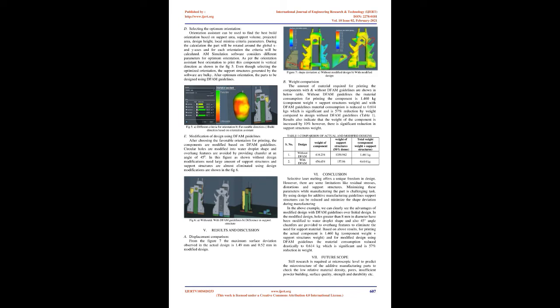To effectively implement this approach, AM simulation software is required for selecting the optimum orientation and DfAM guidelines for design modifications. AM simulation software. Simufact Additive is one of the AM software for the simulation of powder bed additive manufacturing processes, SLM, DMLS, EBM.